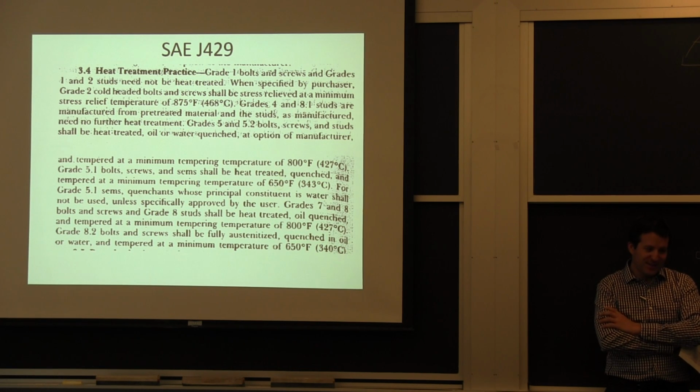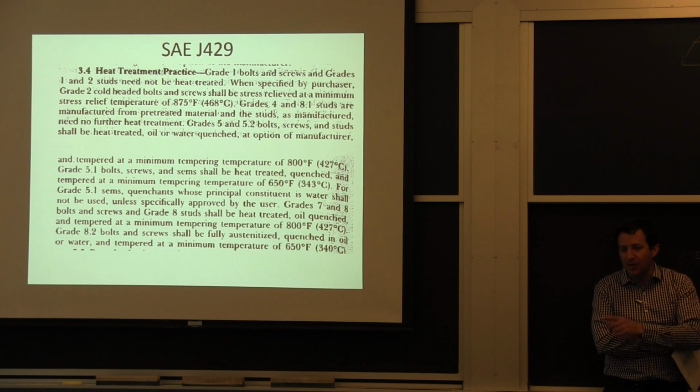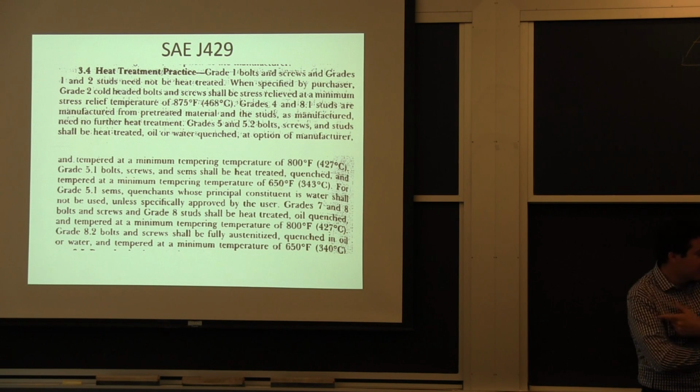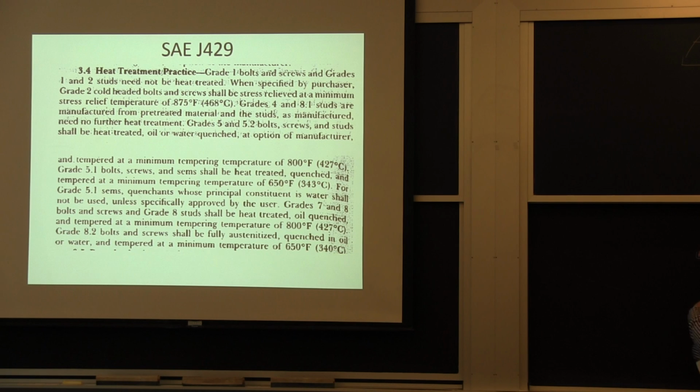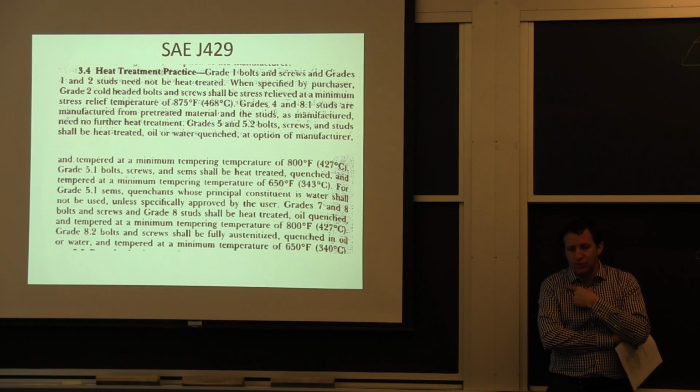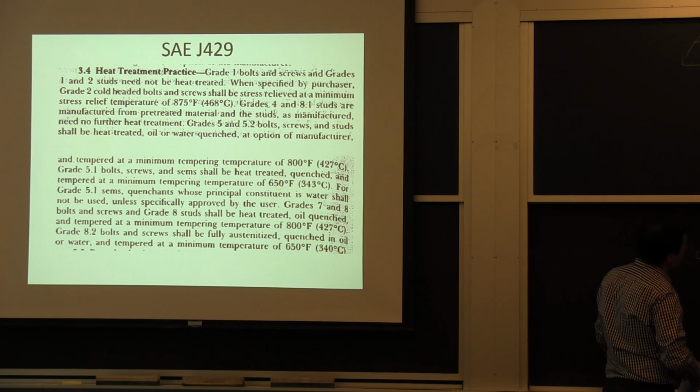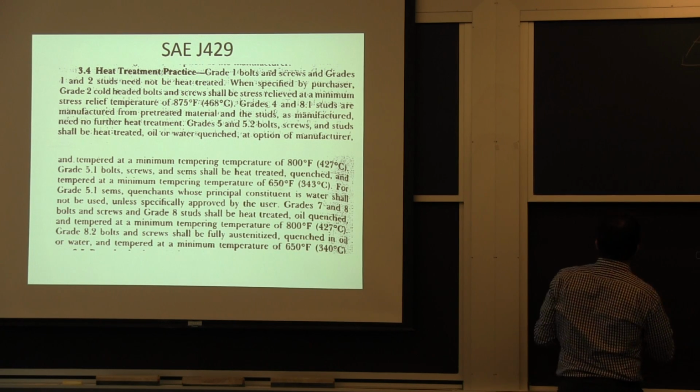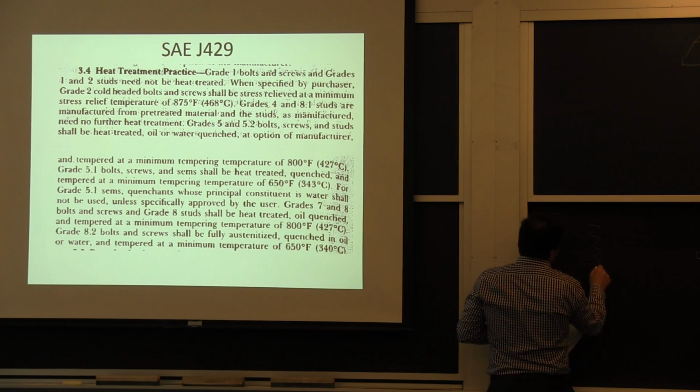So there's a lot that is either specified or not specified in the specifications of material and process, because again, now we really hit more of the process detail with those bolts. Now, why are they doing this? Fasteners are prone to fatigue failures. You have all these threads.